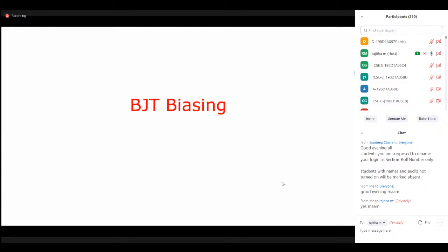So what does an active region mean? Like your PN junction diode, we have two types of biasing, forward bias and reverse bias. But in a transistor we have two junctions. Based on the biasing of those two junctions, the transistor operates in 3 regions of operation. The first is cutoff, the second is active, and the third is the saturation region.